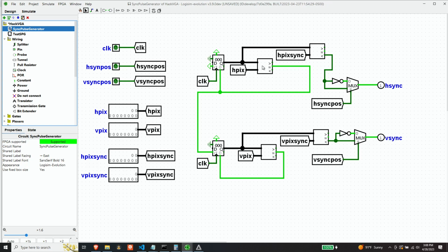It occurs to me that this comparator is obviously not clocked, and so I'm wondering if, when we get to this condition being true, and given that this is an asynchronous reset, there is not enough time elapsing for this counter, which is counting only by the clock, to pick up on the fact that it should be enabled for a clock tick in order to count up by 1. I'm kind of suspecting that may be the problem here.